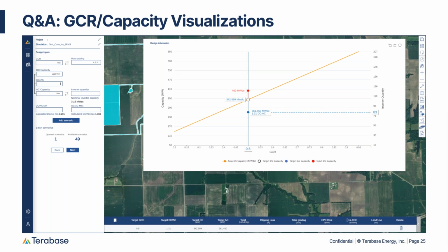When you click on that module or inverter screen, on the top right, there's upload your own module file and upload your own inverter file. That will take you to a screen where you can upload a PAN file or an OND file directly, and it will parse those out and create a module or an inverter file for you to use in PlantPredict and also in Design Pro, because Design Pro uses that database as well.